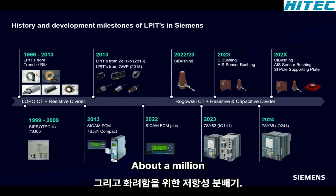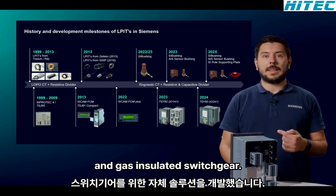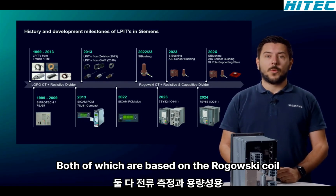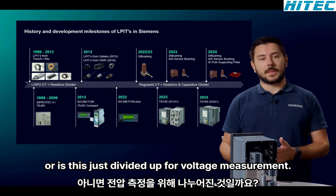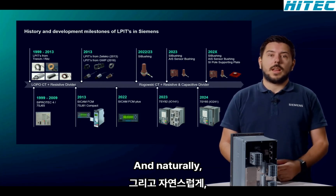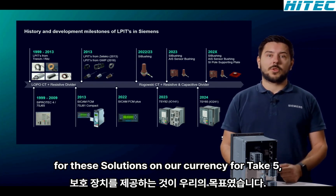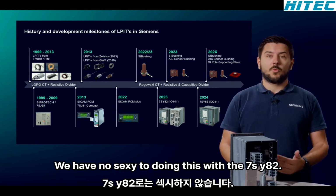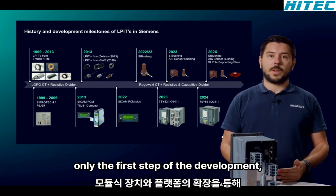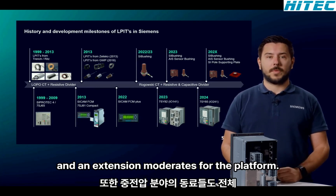But now, our colleagues from medium voltage have also developed their own solution for air and gas insulated switchgears, both of which are based on the Rogowski coil for current measurement and a capacitive or resistive divider for voltage measurement. And naturally, it was our aim to offer a high-performance protection device for these solutions on our current SIPROTEC 5 platform. We have now succeeded in doing this with the 7SY82. And this is, of course, only the first step of the development, which will be continued with a modular device and extension modules for the platform.